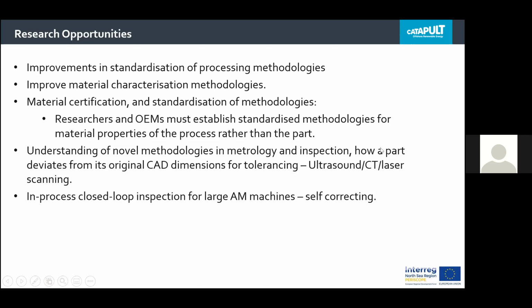Another, I think it's very important to take stock and improve material characterization methodologies. Currently we're using ASTM standards that are for injection molded thermoplastics. So I think there's an open goal for research in the material characterization that would enable better material certification, and understanding methodologies in measuring the part and how they deviate from the tolerances, and that kind of thing.